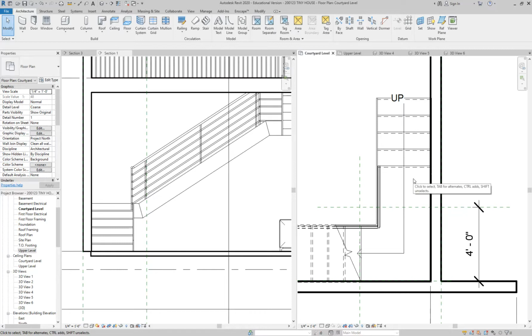So now that we've covered the basics and the fundamentals of stairs, I'm gonna go through real quick what that encompasses, okay? We typically draw stairs as straight runs, right? If we want to draw a landing, how do we accomplish that? We start drawing a line, and then what do we do? We stop, okay? And then wherever we start drawing again is what defines where the landing is.